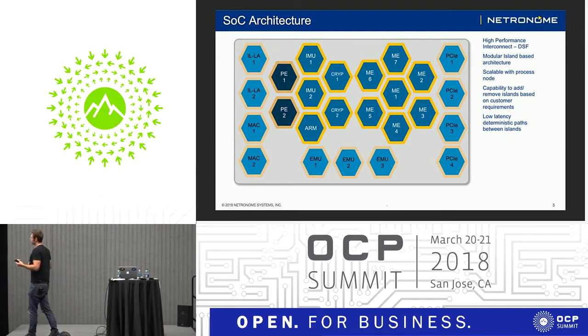Just a quick run through of what the SoC architecture is on the NIC. The 72 cores I mentioned are small flow processing cores. They're specifically designed for networking, so their instruction set is designed for networking, and the way they're set up is designed for networking. You've got a lot of registers for each one of those threads, but you've also got a transactional memory architecture, which I'll go through in a second.